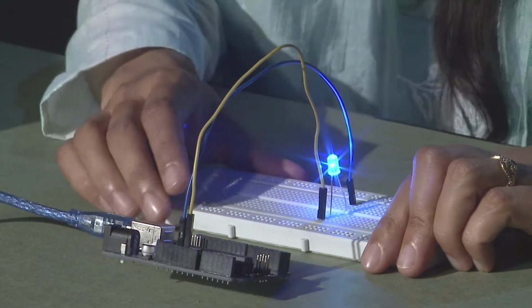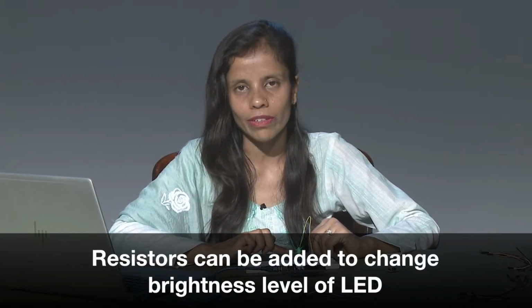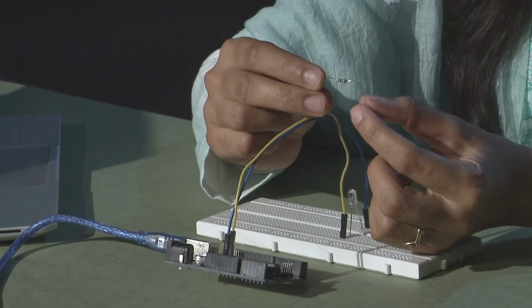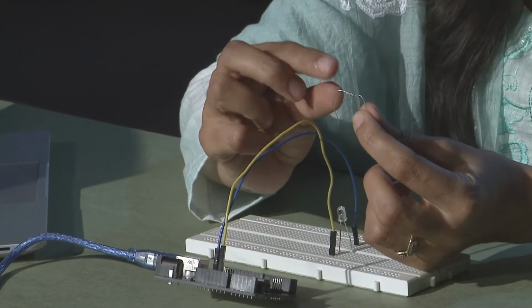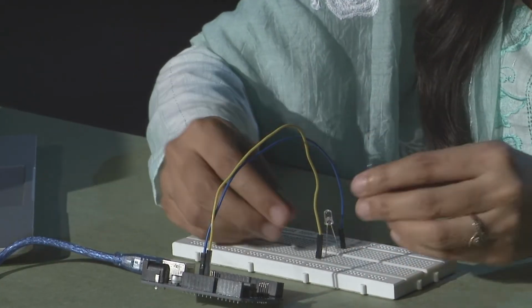As an enhancement to this, we can add a resistor to change the brightness level of this LED. Let me take out this wire so that we can make an additional connection. A very simple terminal connection I have to do with this resistor. I have picked a 220 ohm resistor. You can see the color coding information of all these resistors in the e-content provided with this particular session.